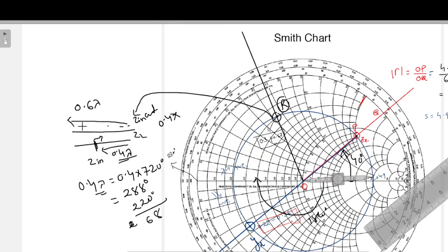So before doing that, we need to know where the maximum and minimum locations will come. In this Smith chart, always from the center to the left side, the minimum voltage point is there, and on the opposite side, it gives me the V maximum point, and this is on the center line. That is because of the concept of short circuit and open circuit. While I explain the Smith chart in detail, we'll explain that at that time.